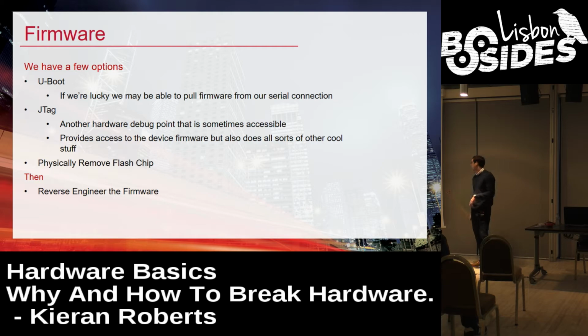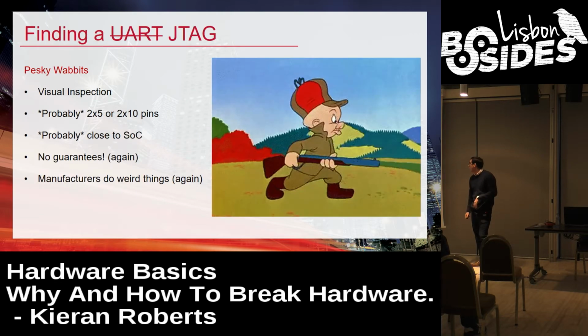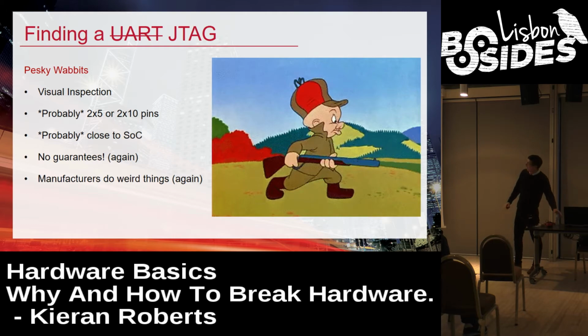Once you've got the firmware, you can reverse engineer it. That's way outside the scope of this talk. So again, finding the thing, back to looking on the board again. You're probably looking for a 2x5 or 2x10 pin array.